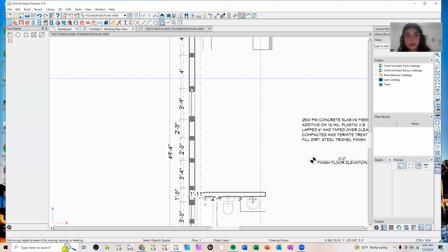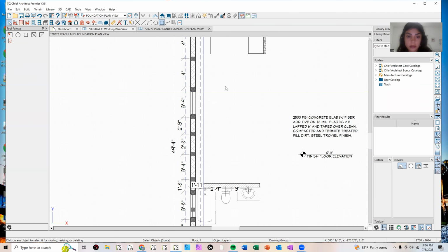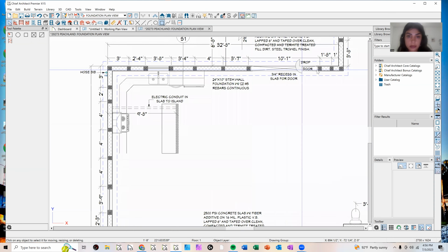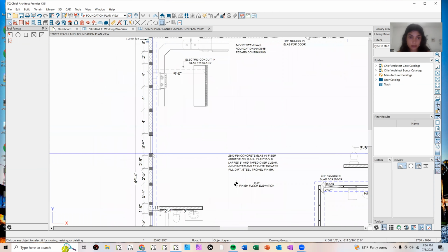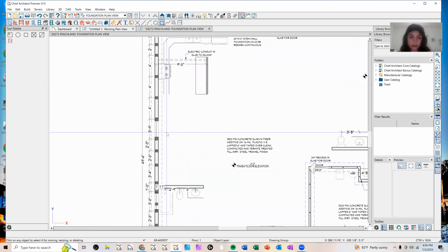So how we tie the lintel to the foundation is with these rebars on the side of the windows. That's why you're going to see one always on either side of the window and on every door. You see, the doors have them too. So you go ahead and you stack all of your blocks here accordingly, 4 feet. And then you come back in, and then you're going to put one on every window on either side, and just make sure that there's nothing over 4 feet.